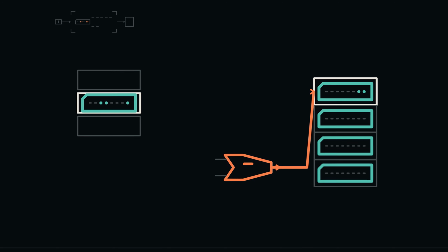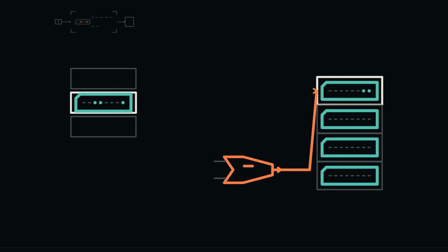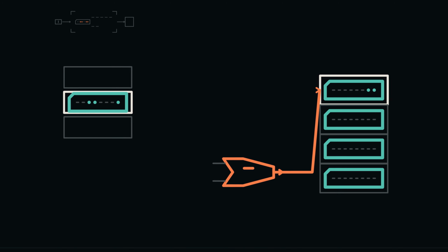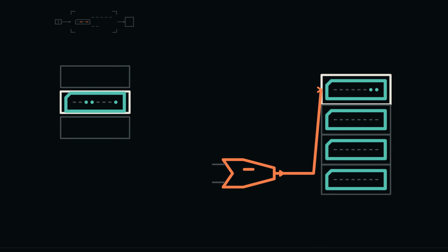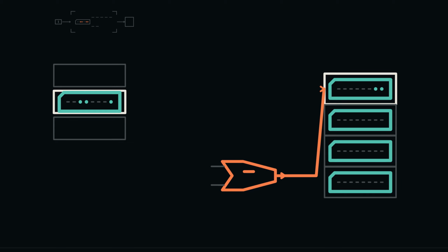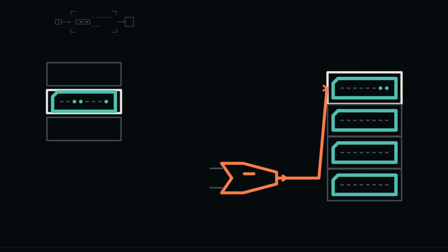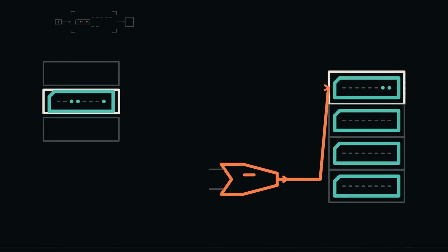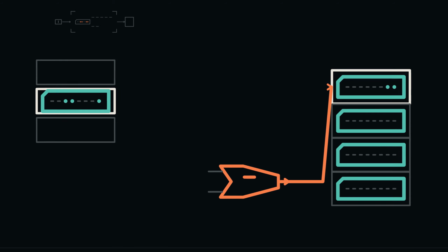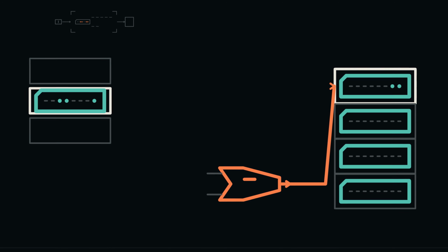The 4 general registers, R0 through R3, are the machine's small working places. They do not decide what their bytes mean. An instruction and the controller determine which register may drive the bus, which destination may capture, and which arithmetic rule is active. The arithmetic unit changes a value. A register preserves the result after that operation is over. That division matters. Without transformation, stored values never develop. Without storage, every result disappears before the next instruction can use it.